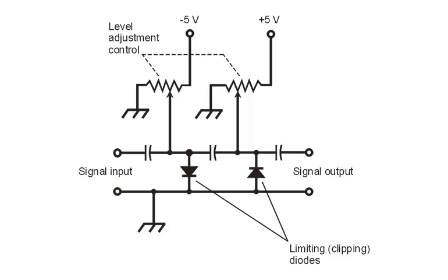Noise limiting. Now, noise limiting is not the same thing as noise blanking. Noise blanking generally works much better because it actually erases the noise pulses from the output. But noise limiting at least will keep these noise pulses, provided that we adjust the bias correctly. These diodes will keep the noise pulses from exceeding the signal that we want to hear. So the correct choice in this particular example is D.